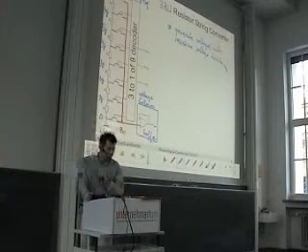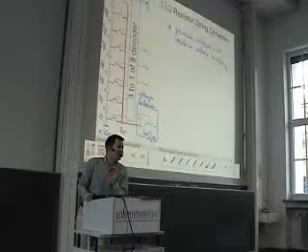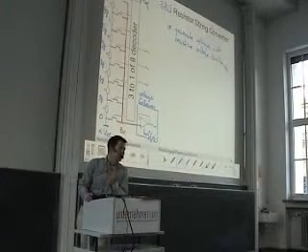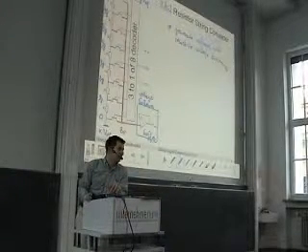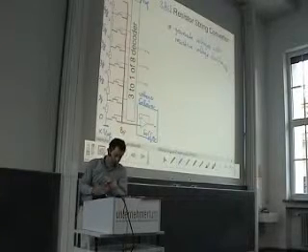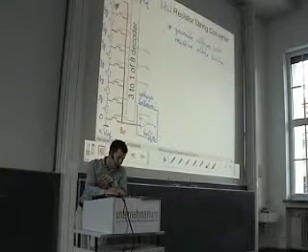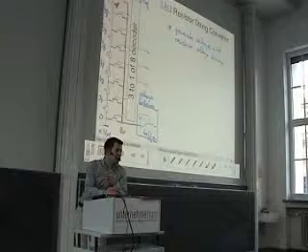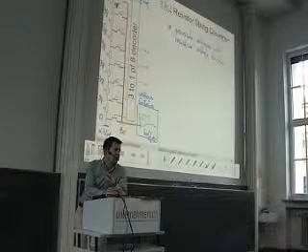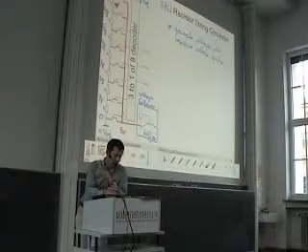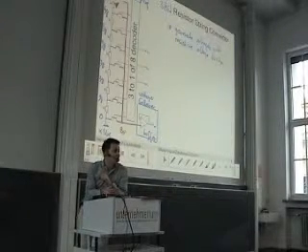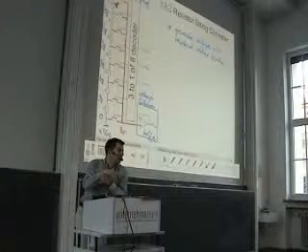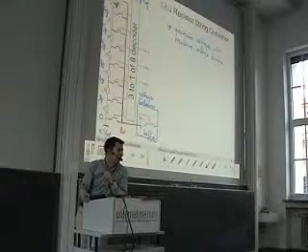So what do you think is a requirement for the reference voltage to make this circuit work? The switches here should work as real analog switches. So you know that an NMOS transistor can act only as a switch if the control voltage is high enough.